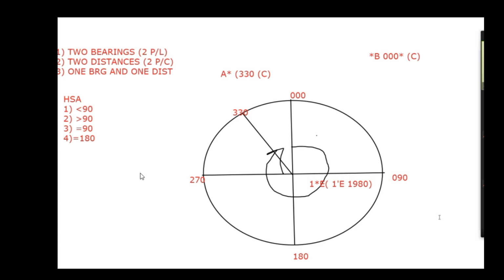Variation depends on place, where you are, where this compass rose is given. It does not depend on the vessel, whether a VLCC, car carrier or small cargo vessel. Variation does not depend on that. It depends on where you are. But deviation, at the same place, varies for various headings and courses. You must have seen the deviation card on board a ship. The deviation card is made with respect to the various compass headings, compass courses.